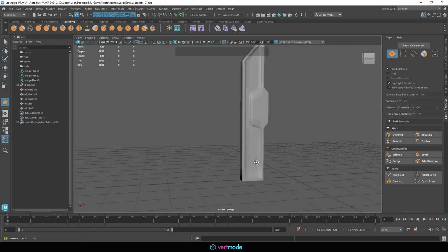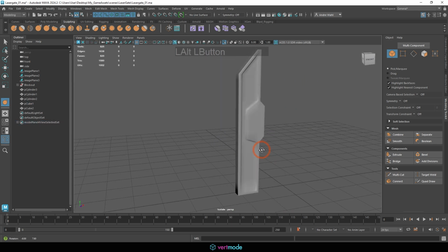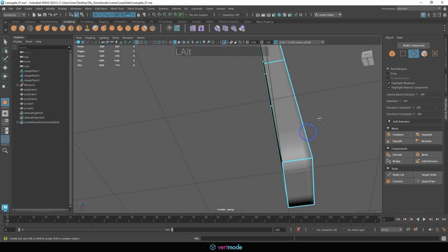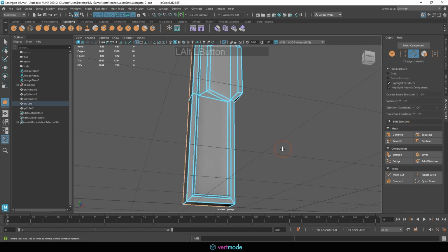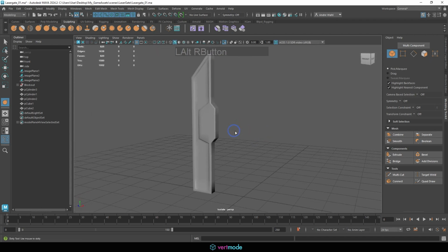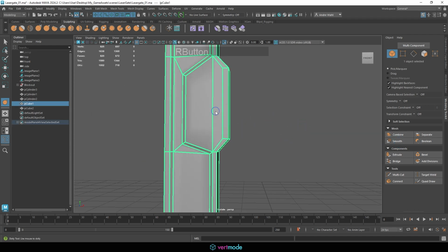You can see the crease tool doesn't quite hold up that great. That's the reason you might want to use bevels instead. I like to think of it as more of a temporary thing. One thing is we do need to make sure we crease these inner edges here to make it hold. But I think with that in mind, we can actually just bevel this whole thing, and we can actually cheat this a little bit and not have to worry about it.